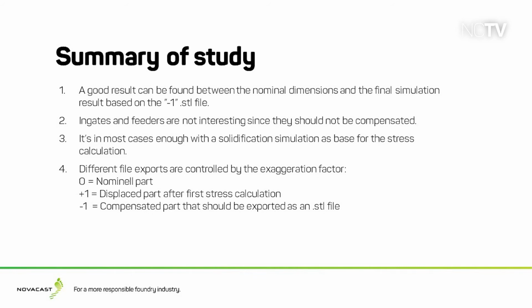And as I said, in-gates and feeders are not interesting to compensate. They should be used for other purposes, so they should not have a compensation. But you can use them, of course, in order to get a better calculation. But you have to combine them, as I said, with a nominal casting part. And in most cases, we can use the solidification simulation. It's enough. There are some rare cases where you have very thin mold casting parts, short solidification times. Then I would suggest to use the full. And for high pressure die casting, definitely you should use the full, of course.